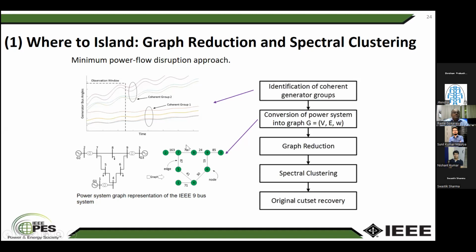So on the top graph here, after a disturbance window, the observation window is where we do the analysis. As I told you, after an initial major disturbance event, the natural split that happens is into 2 coherent groups. Multiple groups only happen at a later time instance. So the first piece of analysis we do for stability is based on 2 coherent groups. This is the observation window here.